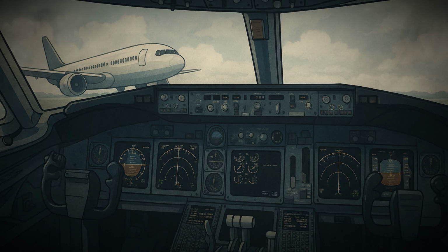At higher speeds, induced drag decreases because the wings require a smaller angle of attack to generate the same amount of lift. Engineers use winglets, which are vertical extensions at the tips of wings, to reduce wingtip vortices and minimize induced drag. These winglets improve efficiency, save fuel, and are now a common feature on many modern aircraft.